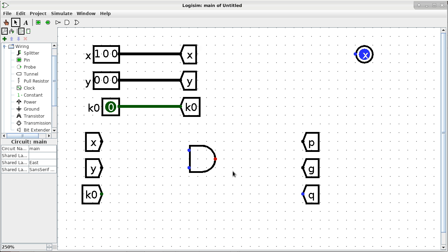Well, but nothing is really hanging in between, okay? Because depending on the length of the wire, it is an antenna, okay? So it becomes an antenna, which now depends on, okay, did someone just turn on the microwave? Then it becomes a 1, okay? And you don't want your circuit to be susceptible to that sort of stuff, right? Somebody's phone just rang next to you and the circuit decides to do something else. That would not be good, unless it is a cell phone ringer detector. Then by design, that's what it's supposed to do. So do not leave input pins unconnected, and that's the reason why we don't want that.